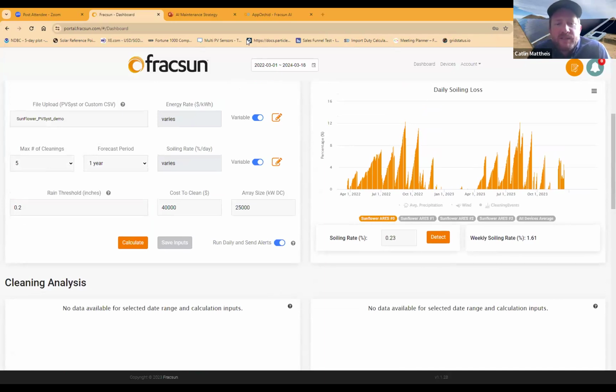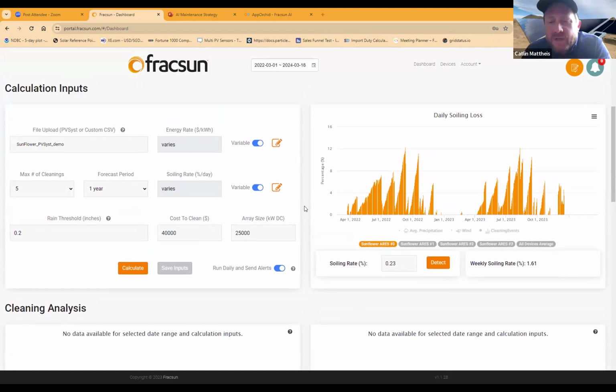Oh, that's you asking. Okay, so at the end of the day, we measure this delta across these two surfaces, and then we ultimately come to a total loss value for the day, and that is represented here. I'll mention this is an operating asset. It is a real field. This gets updated every single day, warts and all. And then you can see here, soiling loss will accumulate fairly linearly. To something that Thore mentioned, soiling rate is a very important consideration. In our portal here, we can highlight a specific area of this graph to calculate that rate automatically down here.